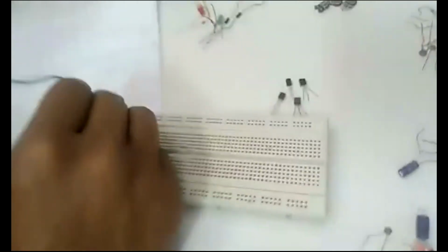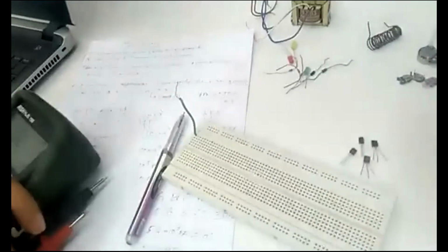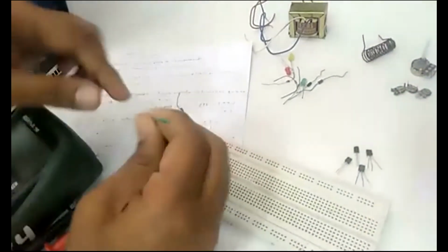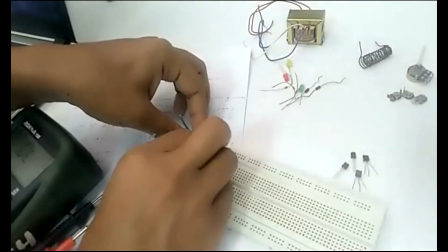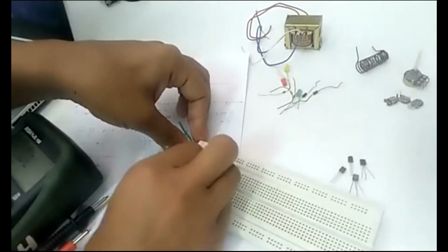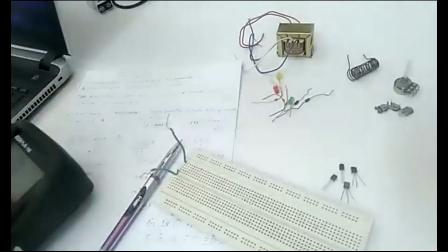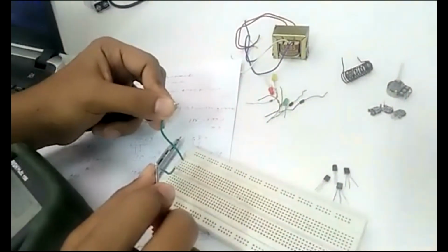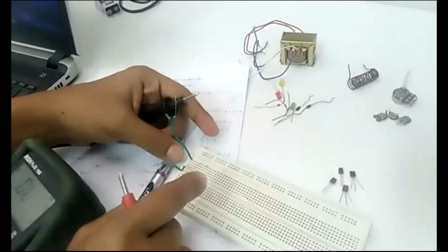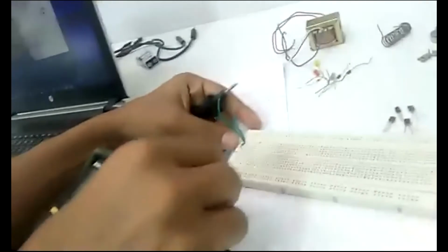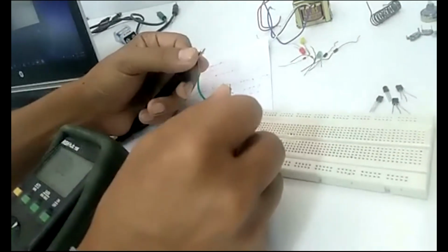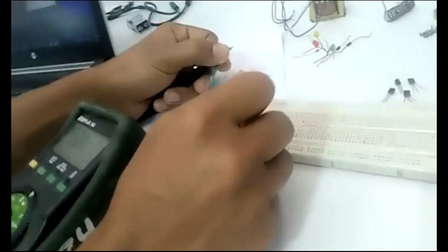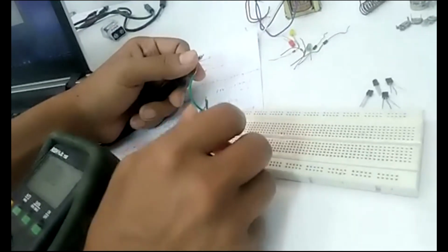Let's say I am connected over here. Then another one, we are going to connect here in the same vertical line. So how are we going to check it? If we connect it and we get the sound, then they are connected, meaning there is no resistance. They are connected through the same connector. Now, if I put it into the next one, then we are not getting the sound, which signifies that they are not connected, meaning they are disconnected.